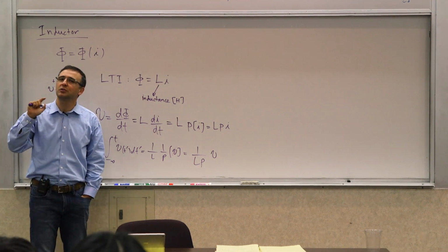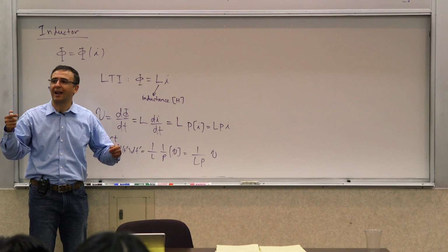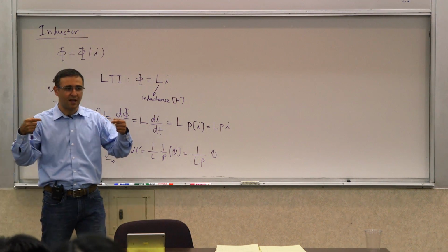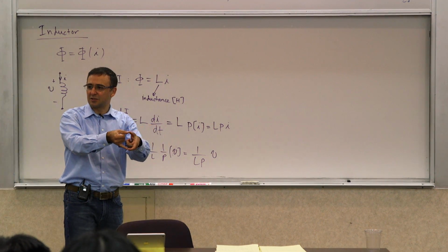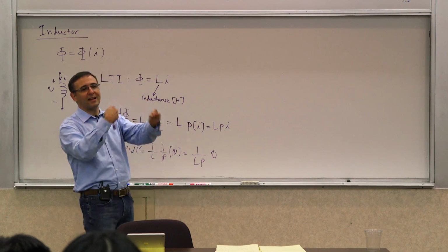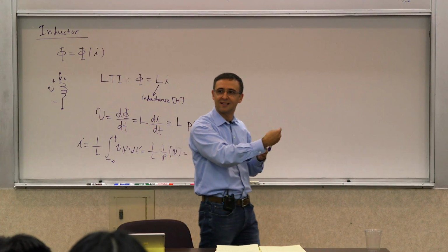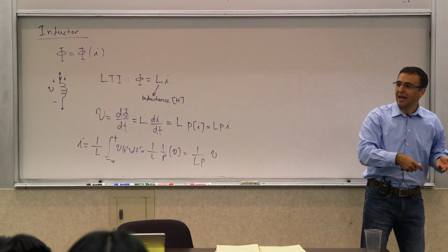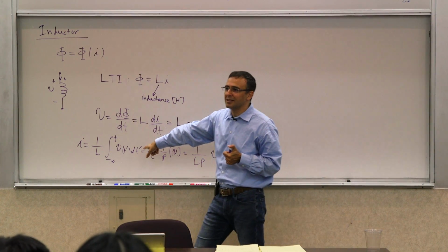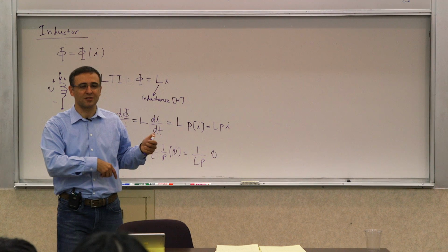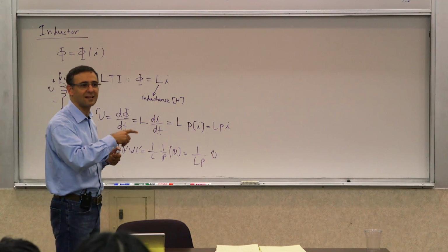Now, in practice, we won't really use a resistor because of the unilaterality and bilaterality we talked about. If you just connect a resistor to it, that would affect things backward too. So you need some sort of buffering, an amplifier or something like that, separating them. But if you do that, then you have another voltage, and then you can put another capacitor and get the second integral, or put an inductor and get the second derivative.